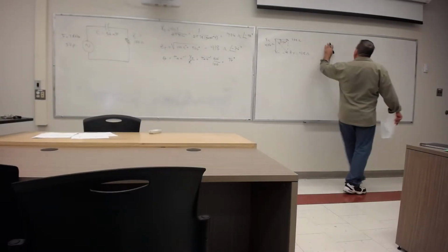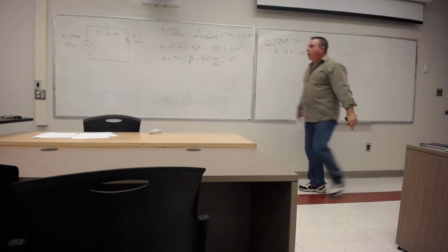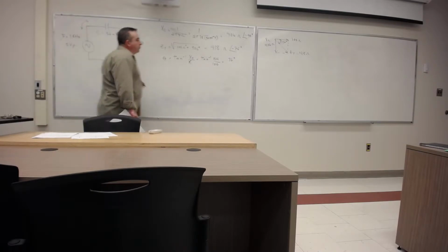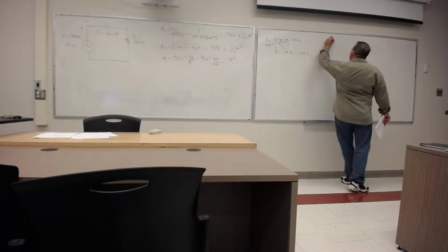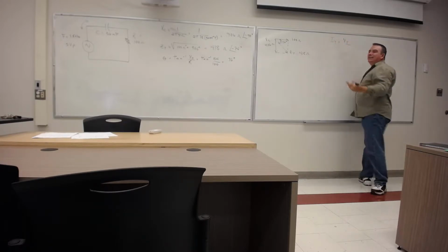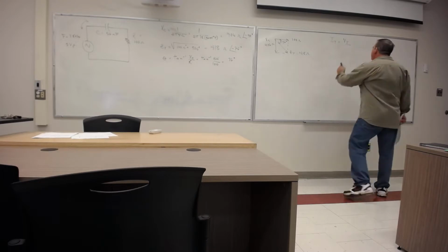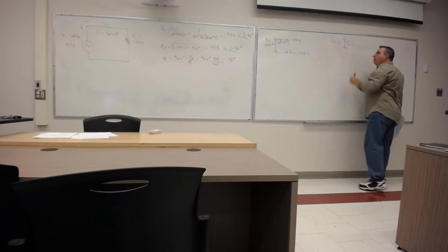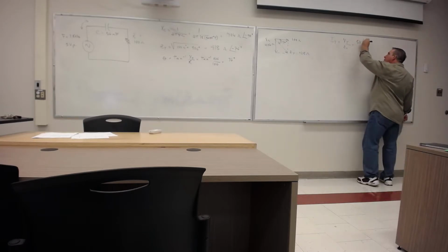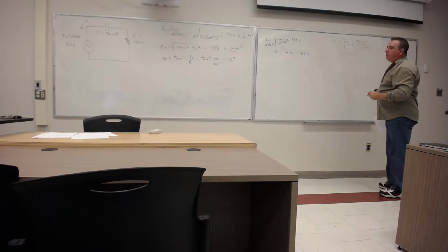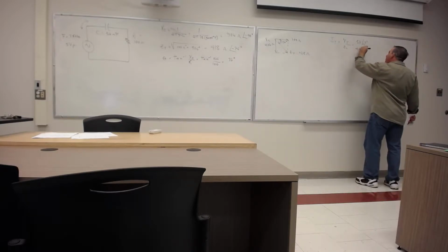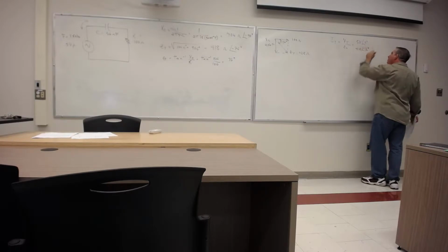Next we can figure out our total current. So we've got an AC current flowing through there. IT is going to be our total voltage divided by, well, this isn't resistance in this case, it's impedance. So we'll go voltage total, 5 volts at 0 degrees, divided by the total impedance that we found to be 418 at negative 76 degrees.